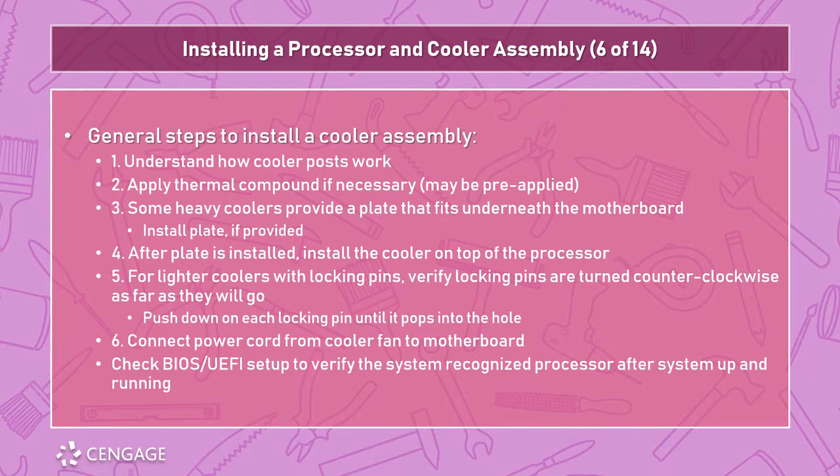Now, if you have a heavy cooler, or if you have a cooler that's particularly tall or awkward, there may be a plate that fits underneath the motherboard that has to be anchored in place. This is just a backing plate, simply because the printed circuit board may be thin enough to where eventually, if it's put upright, the stress and weight would cause the board to bend, buckle, or snap. Then we can go ahead and install the cooler. If lighter coolers have locking pins, make sure you're aware of whether or not they need to be turned clockwise or counterclockwise.